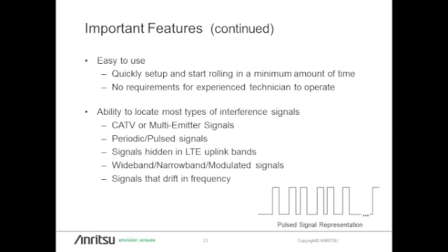And that is, when it's pulsed. And then it just keeps taking the maximum. And then as you drive, as you're going towards the interferer, that pulse will grow in magnitude or power level, as you see on the spectrum analyzer. So it's a feature with the spectrum analyzer that really gives you a good capability with this type of signal.